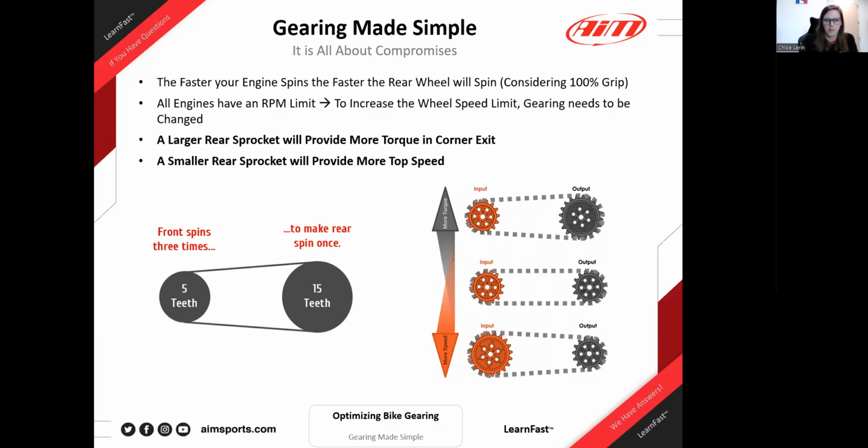So for example, I was at Road America this weekend and I was on stock gearing, which is a 16/45. And that was way too short of a gearing. I was running out of gear. I was spinning 6th gear on the straight and really not going that fast. And I'm going back there on Monday. I'm likely going to go to a 16/43, which is going to increase my wheelbase and give me more stability, because Road America really doesn't turn that much.